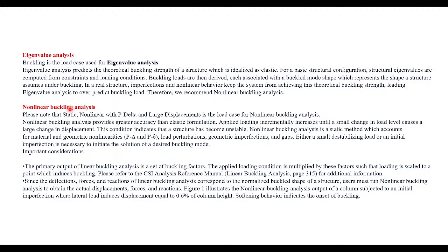So we always prefer non-linear buckling analysis if you see the component is trying to fail in buckling in the static analysis. Even if it is not failing, we always recommend considering non-linear buckling to validate your components, if your component is prone to buckling. That is important.